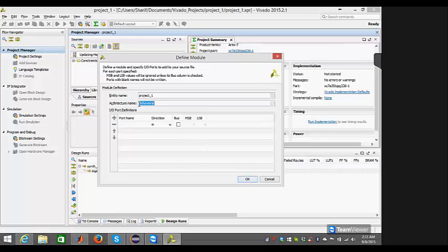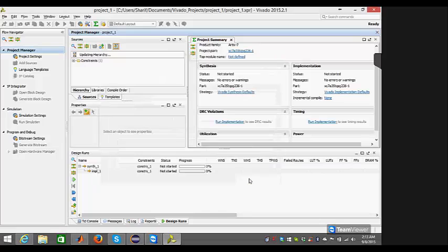Since in this lab we just have inputs and outputs of just switch on and switch off for the LEDs, I'm just going to do mine in data flow, as we've learned in class. For this tutorial, I'm going to do one switch and one LED, and then you can do the rest. So I'm going to assign one input and one output. So one switch, one LED, and I'm going to name my architecture data flow. And I'm going to click OK.